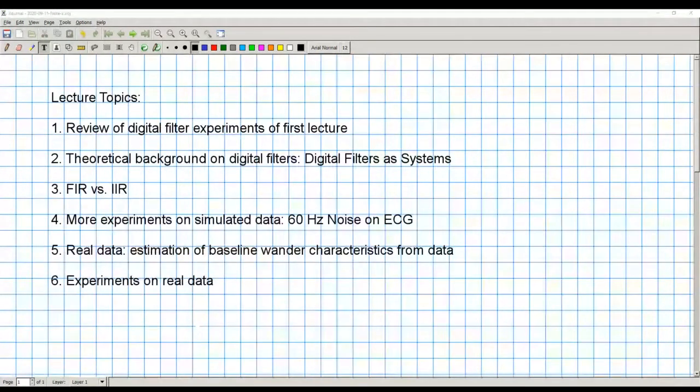This happens when you have a poor filter in your ECG, and some of the noise from the AC in the examination room gets superimposed on your ECG. So we're going to simulate that, generating a signal that has these characteristics. The reason we work with data like this is that we know exactly the frequency of the noise. We know that the noise is at 60 Hertz. So we're going to get started on designing suitable filters for that.